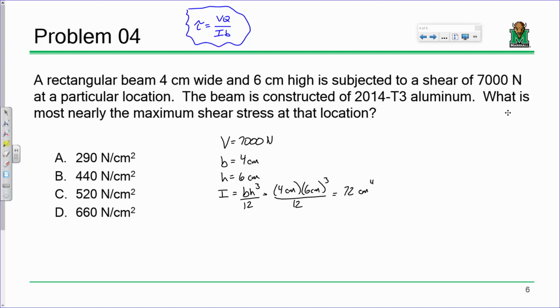The reason why is this. When I bend these papers, when I bend this notebook, what's happening to the papers? They're just freely sliding, right? It's why here they're flat, but when I bend them, see how they're separated from one another? When you have a solid beam, those internal layers develop stresses in between them, okay? That's what the shear stress is, that's where it's coming from.